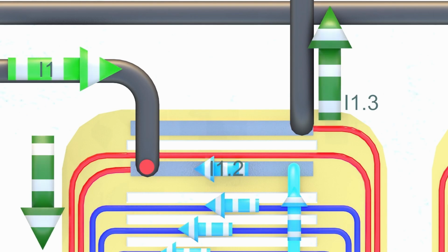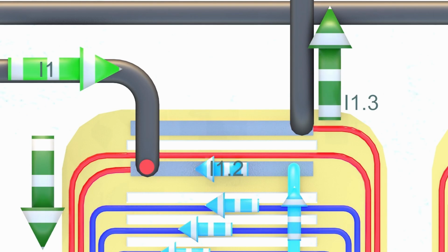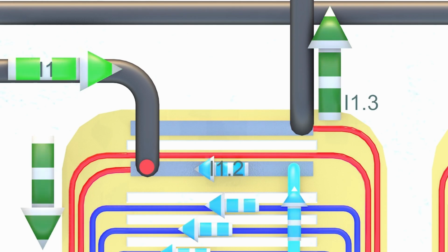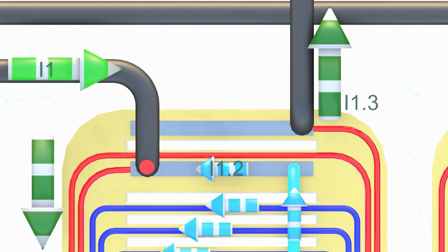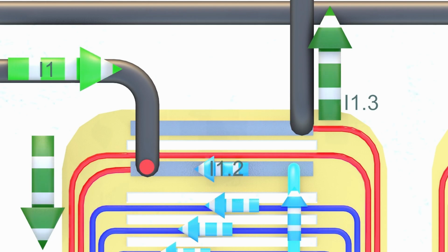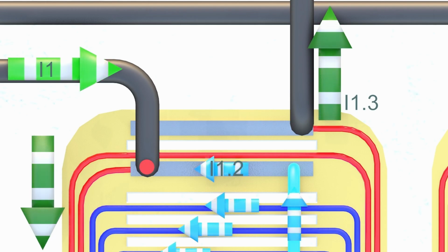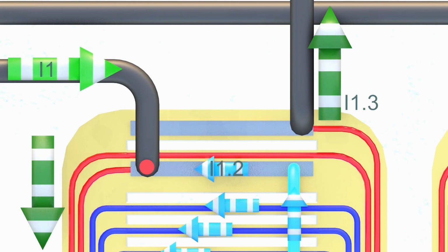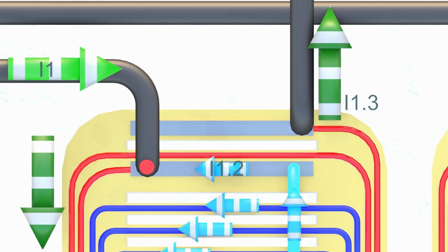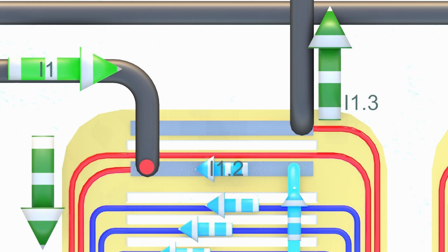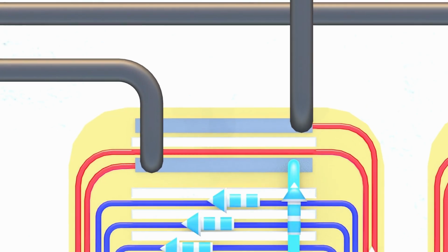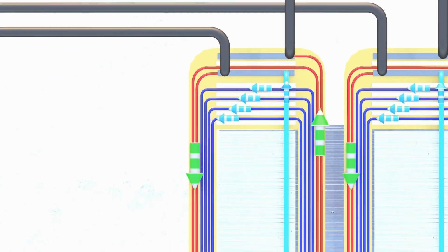When there is an unbalanced load due to the shifting of the floating neutral point, this can counteract the imbalance and restore balance. Pretty straightforward and well-known electrophysics. Because the primary current and the current of the secondary coil must always combine to form the total current in the end, Kirchhoff's rule applies here as well. This means that less neutral current will flow back to the medium voltage transformer. Electric energy losses that have to be paid for, but bring no benefits.